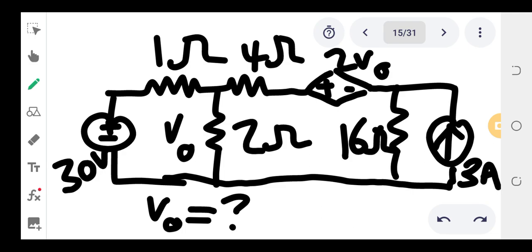As usual, nodal analysis is the modified KCL. So we need to come up with the KCL equations. Then we apply our Ohm's law. We substitute where there is current with resistance and voltage, current in terms of resistance and voltage. In this case, we have been asked to determine this Vo.